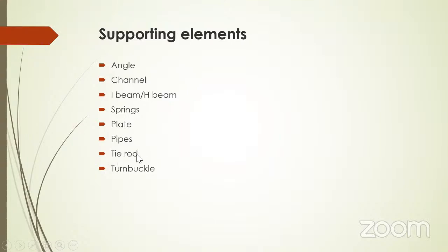And then tie rod is nothing but a kind of stud bolt arrangement. We can adjust it according to the pipe load or the initial position. And then turnbuckle, we have already seen in the pipe hanging support, a turnbuckle will be there. You can see turnbuckles in many areas, like transportation, where they fix the object in a truck.